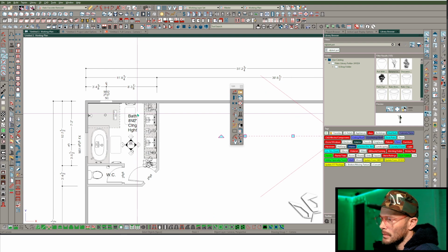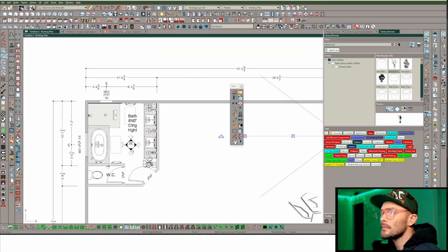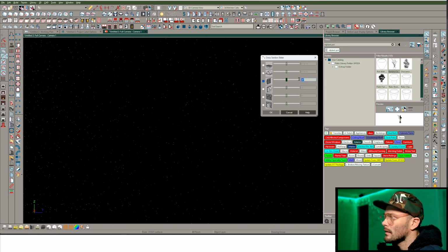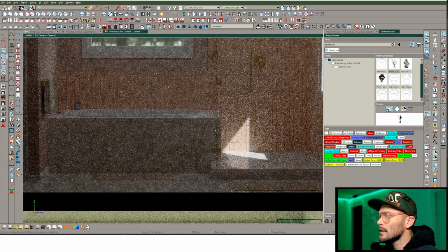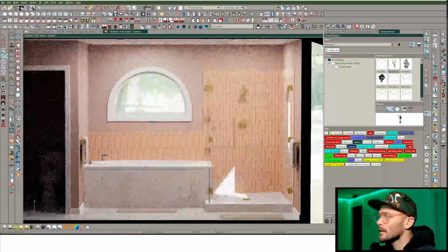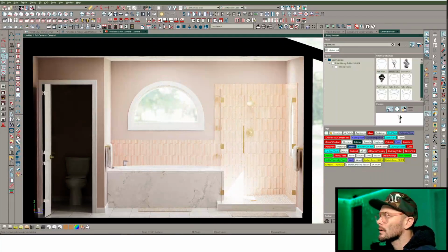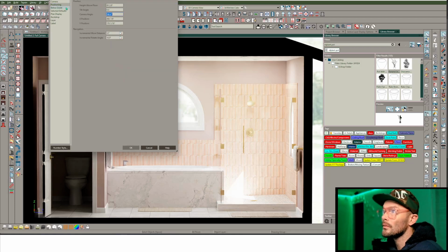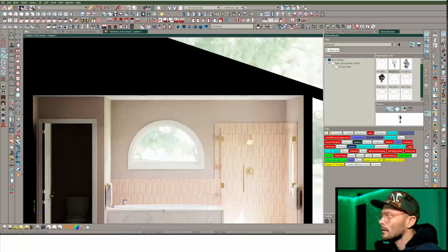And then I want to cut this right in front of right here, maybe. Okay, so I'm going to look at my X coordinate, -161. So let me go back to this camera and we'll turn on a section cut that is -161. And we should be able to, you guessed it, see this guy, right? We'll have to back this camera up a little bit. But yeah, look at that. That's looking pretty good. Let's just make sure our positioning's all good. So no tilt angle, 180 is still good. Height above floor is a little high, but that's okay. Yeah, let's see.